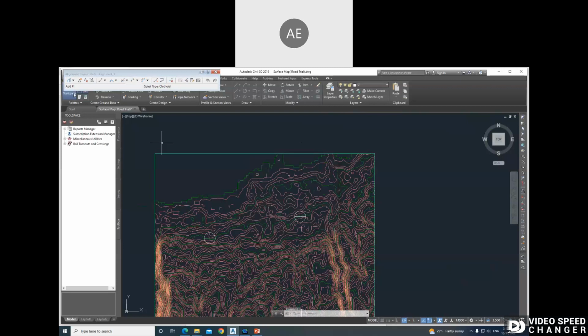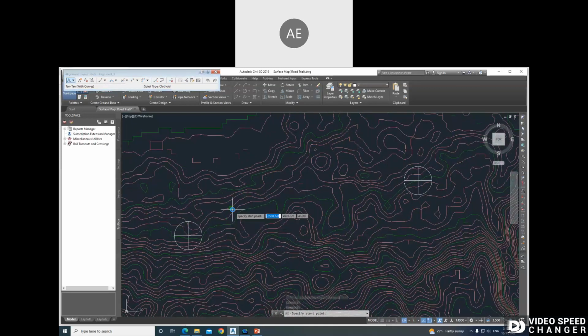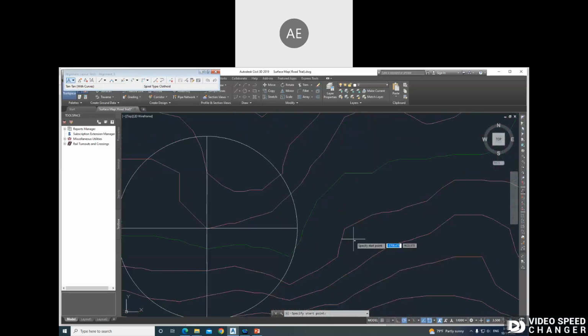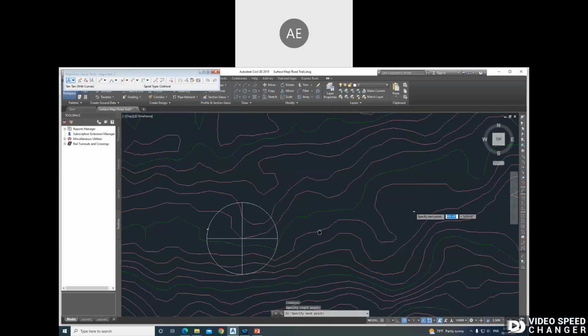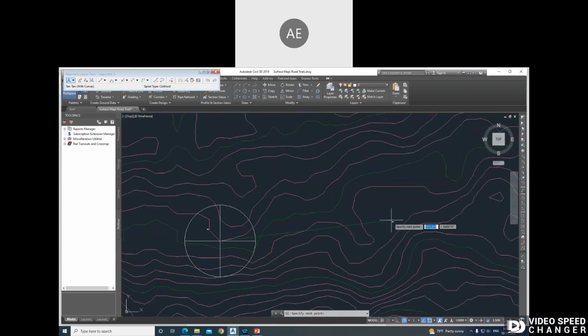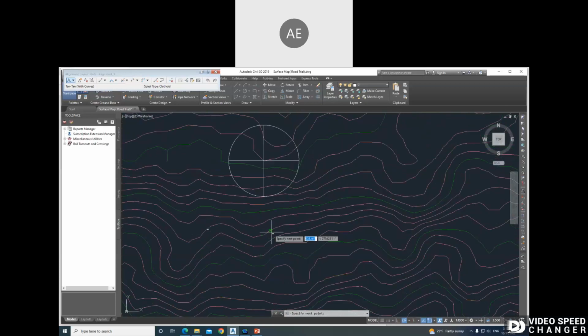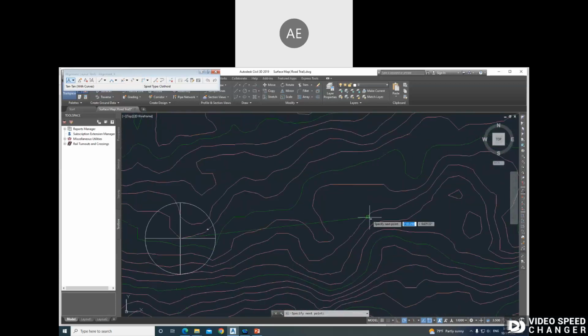Now we go back and we try to draw the curve. I'm going to draw it randomly. I'm not going to talk about how we draw it, because you should know from transportation how to lay out the alignment. But just to give you an example, we start at this point. Okay, we click on it. Now, look, I'm going to go in this direction with the contour lines, not opposite to the contour lines. Otherwise, I'm going to basically go upward with the elevation. I need to go with the elevation at the same level. Otherwise, as I said, we'll have a lot of area of cut.